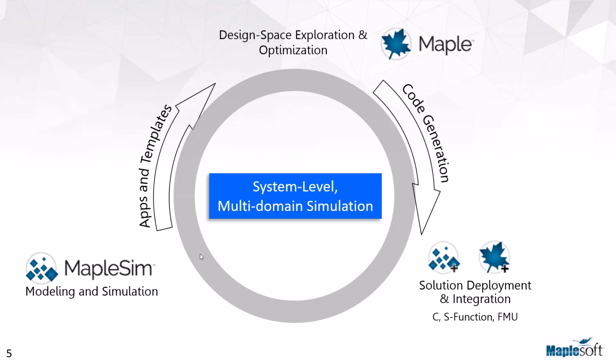The main way to do this is to export an FMU, a functional mockup unit, and this opens the door to the world of simulation in other tools, as well as to do virtual commissioning and connect our model to a PLC and to test the control structure in the PLC, for example.